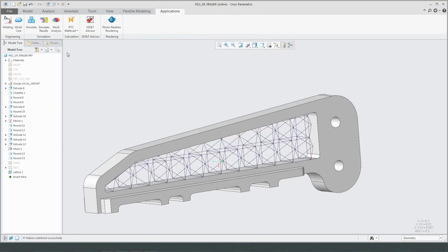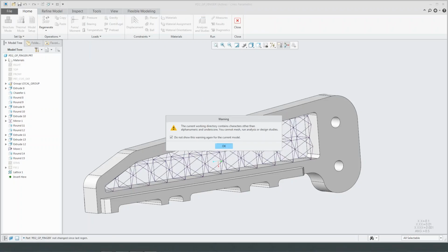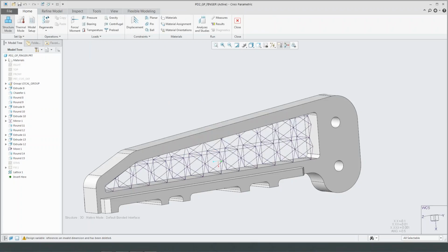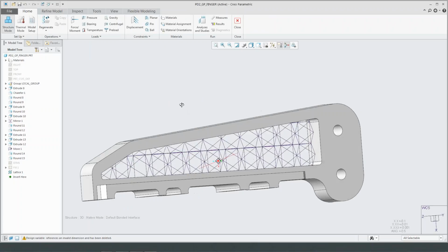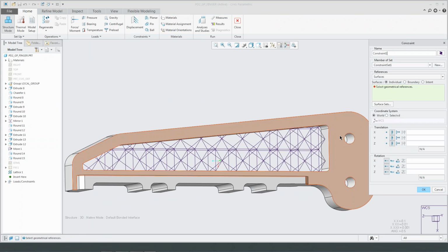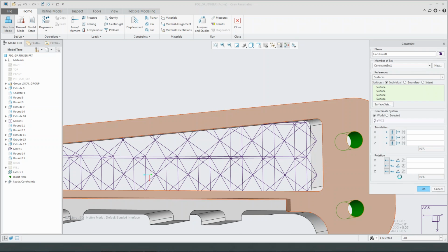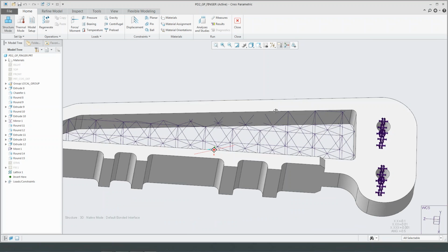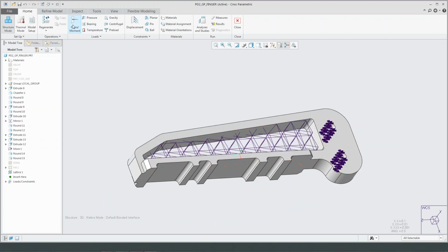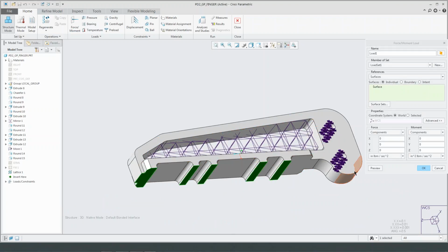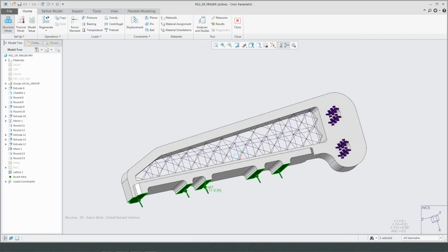And then under applications here inside of Creo, I can just go to my simulate extension. Same UI, now I have tools for how I would simulate this. So let me lock this component down like I would in a physical test lab. And then also apply my force. So this is a gripper, so the force would be on the surfaces down here as it closes, and I can apply an XYZ component to this force. Preview what that looks like, and accept that off.